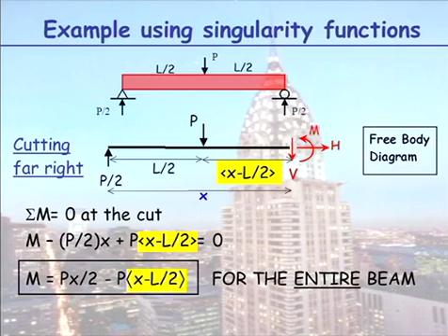So, let's go back to that point load case now. I'm going to cut my beam as far left as possible. This time round, when I have my x minus term, it's in my pointy brackets. So when I cut the beam and take moments, I get this expression here, M minus P on 2 times x plus this P load acting times the yellow bracketed form. And this expression now represents the bending moment for the entire beam. So how does that work?